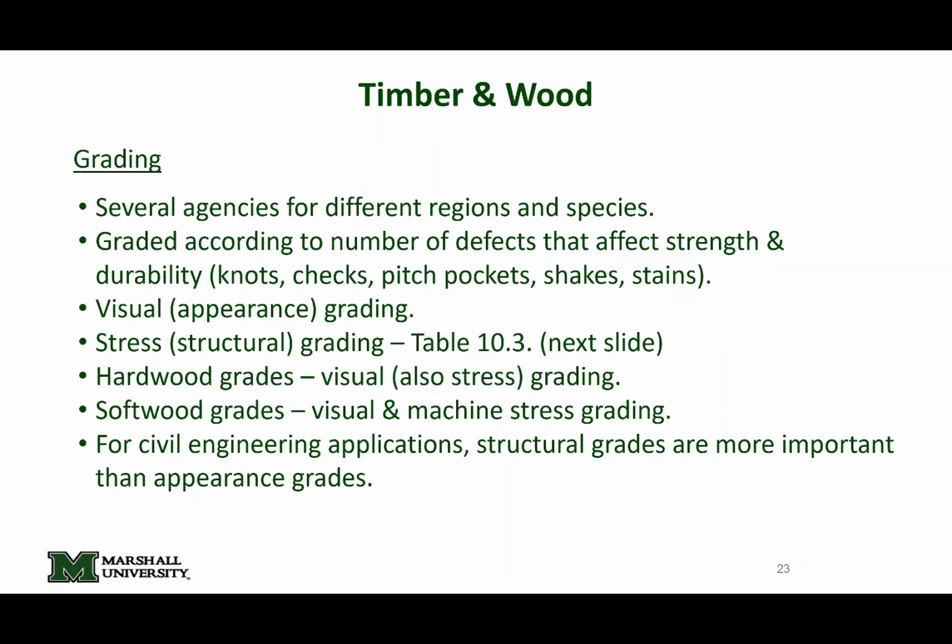There are visual appearance grades as well, and I'll show you some specific stamps of that. In my head I'm thinking about glulam products. There are glulam products that are meant for visual appearance, and then there are glulam products that are meant just to hold up loads. You'll see, for example, in some spec houses they'll use glulams under the first floor to hold up a big section of the house. It's a really big element that's hidden so that nobody can see it, so it has a different appearance classification. Certain elements have a really high appearance classification in case they're going to be stained, so that affects things as well.